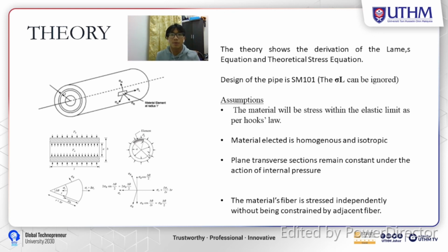Assumption, the material will be stressed within the elastic limit as per Hooke's law. The material selected is homogeneous and isotropic. Plane transverse section remain constant under the action of internal pressure. And lastly, the material fiber is stressed independently without being constrained by adjacent fiber.